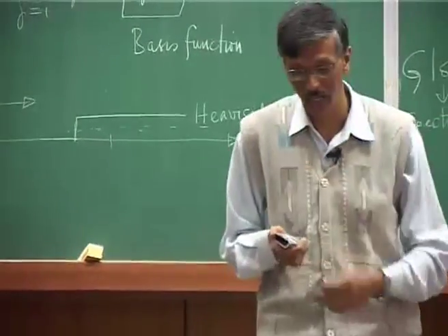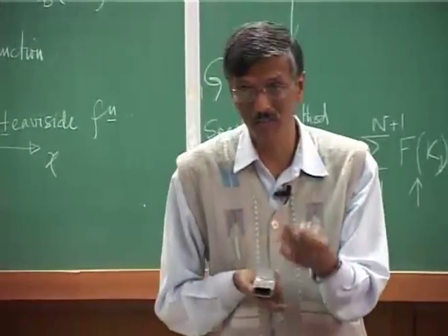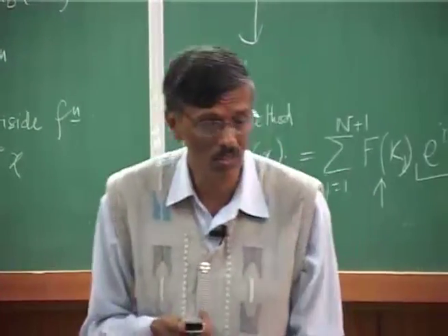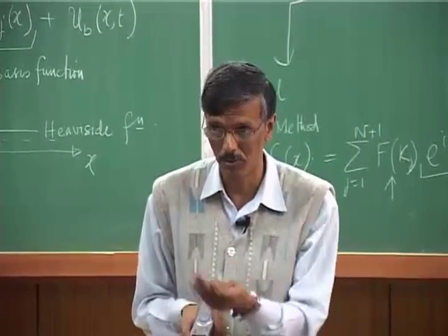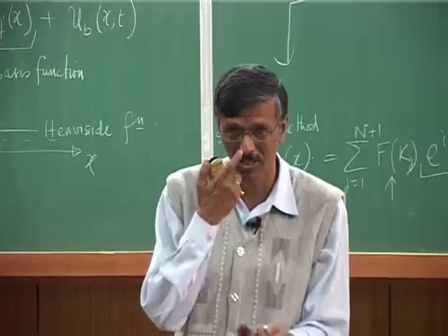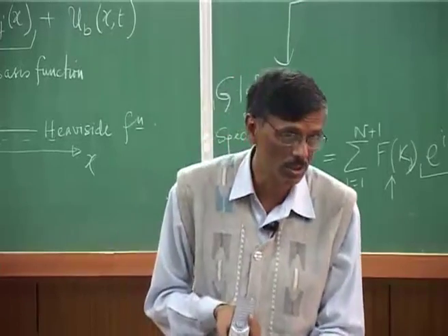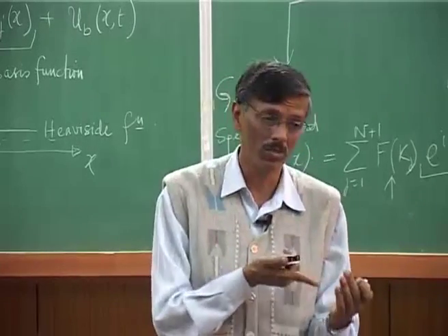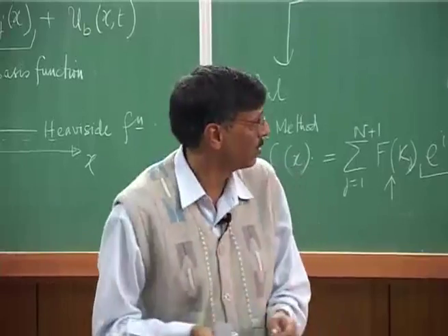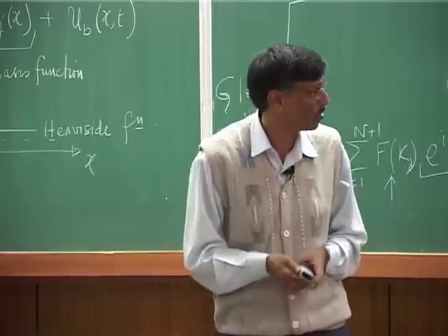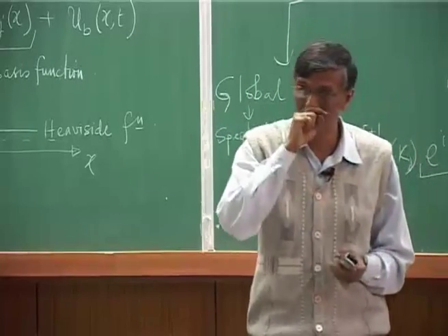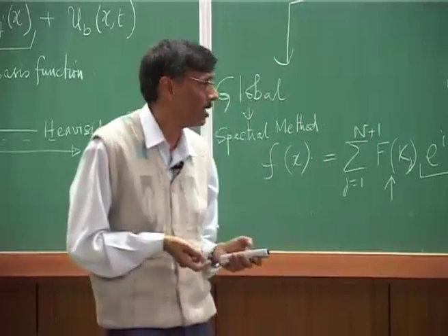That is what we have seen, that even a first order accurate method in solving the convection equation turns out to be the most accurate method. We recall that in the 1D convection equation, we saw that first order upwind gives better solutions because it supports the physical principle. However, if you do not do it carefully enough, then we have also seen that there could be excessive dissipation coming into the picture.